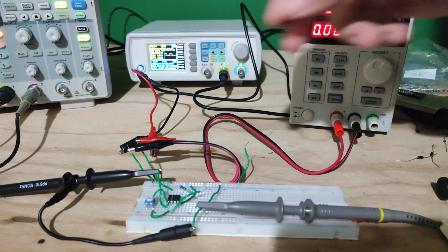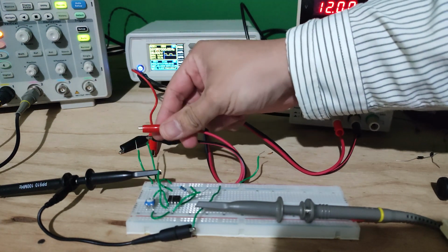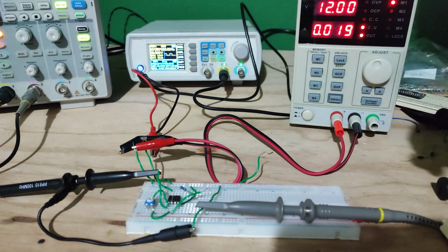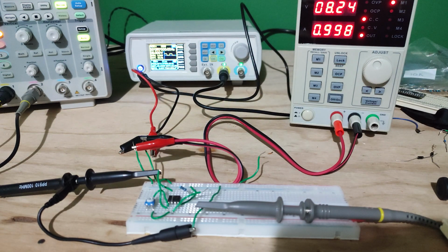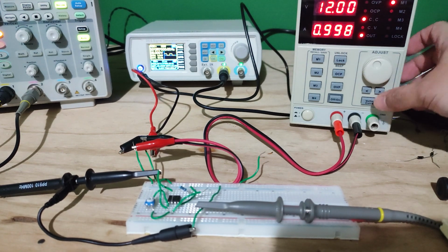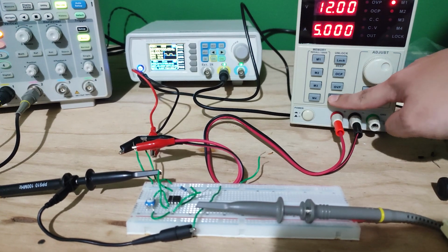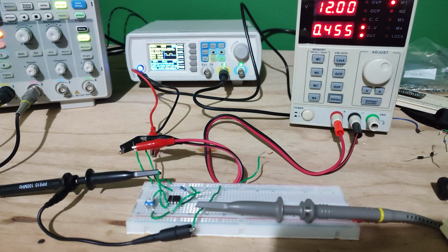So now we're going to see what happens when we switch the polarity of the supply. We can see that the output current consumption goes to 1 amp. Let's increase the limit. And let's wait to see what happens. And the magic smoke comes out of the op-amp. So we are basically burning the op-amp. It is not going to be operating in any way.